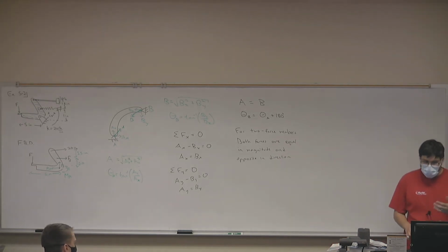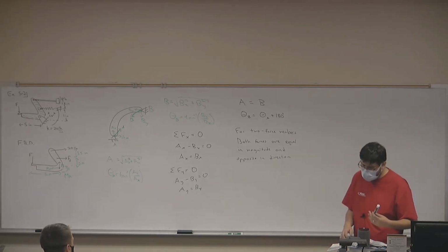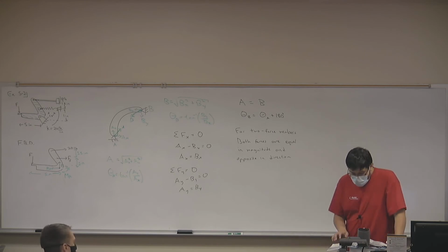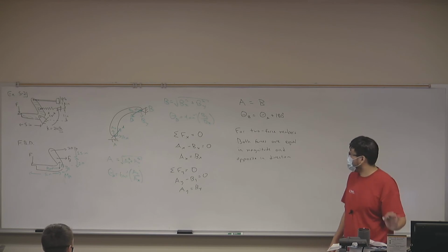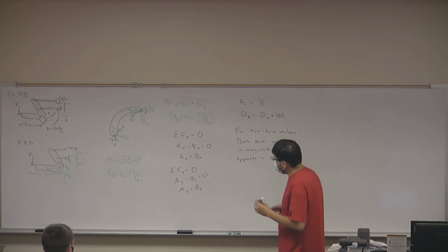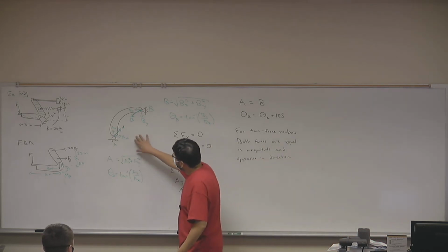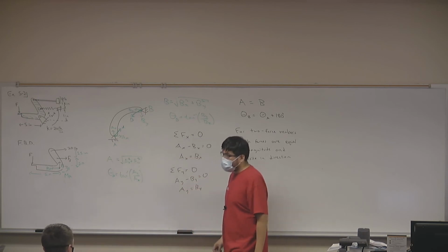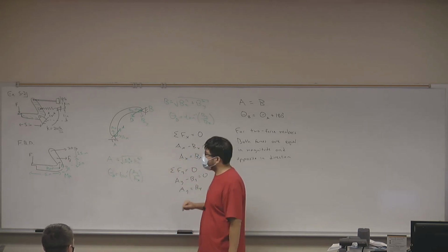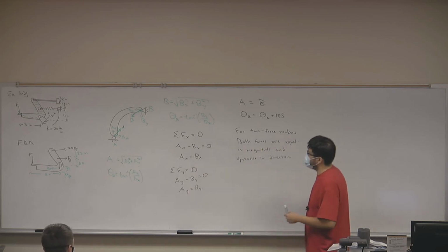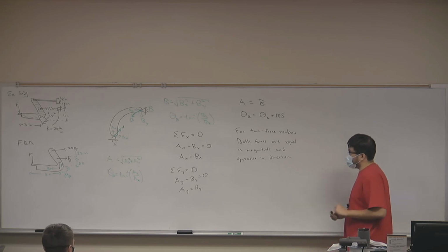So this is a two-force member. And hopefully you can see how we identify this two-force member, or why we would want to care about it. Because what this tells us is that both forces will have the same magnitude. So really, if we can find one, we will know the other. So that's pretty much all I have to say about two-force members, really.